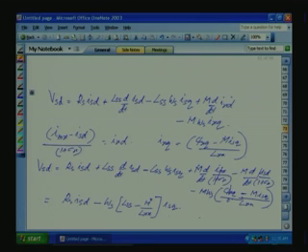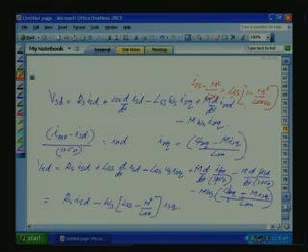See, this LSS by LRR term, LSS minus M square by LRR, we can write as LSS into 1 minus M square by LRR LSS. So this will become a constant, that we can get sigma LSS.